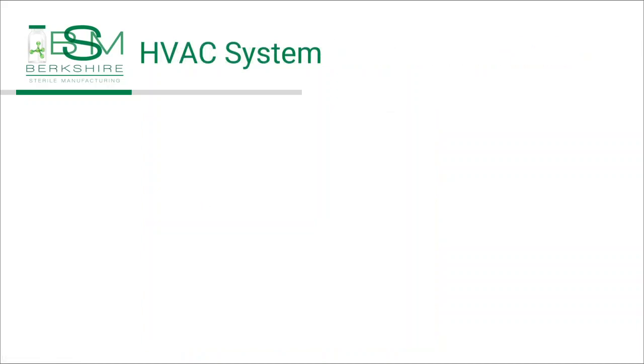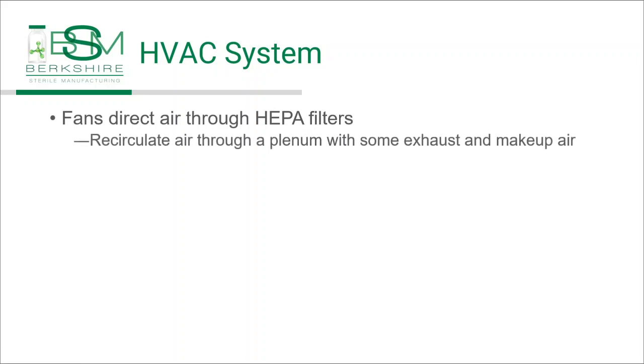Okay, the HVAC system. We know that we need a laminar flow, or a flow of air through HEPA filters to produce the grade A air that's being used inside. Usually the air recirculates through a plenum with some exhaust and some makeup air, or you can get systems that have 100% exhaust and 100% makeup air.